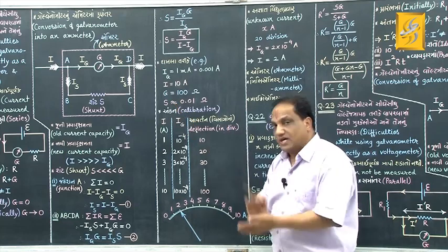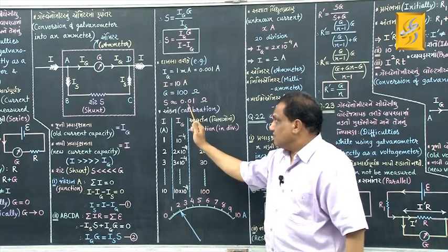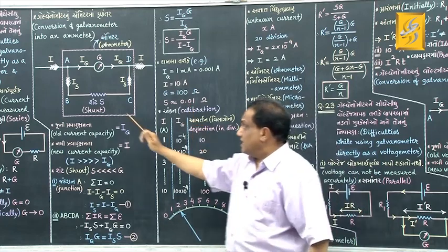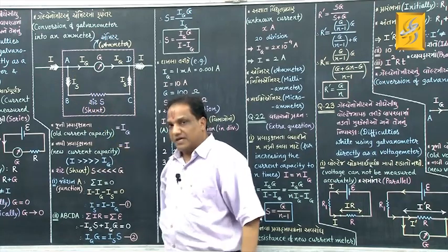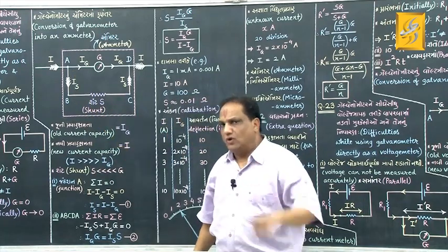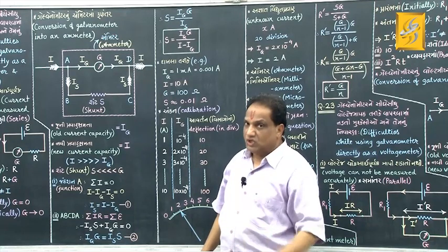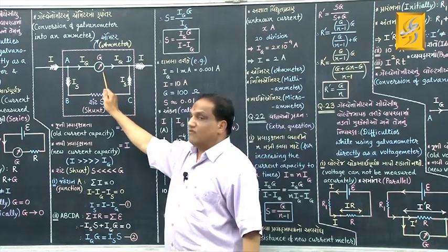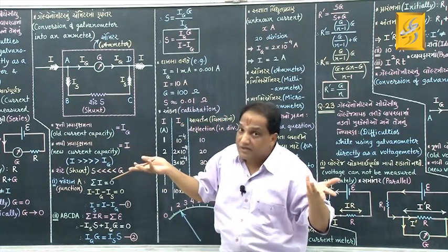Suppose you are finding this shunt, means it will give you ammeter? No. This much value of resistance you must connect in parallel with given galvanometer. Correct? Suppose you have connected, means it will give you ammeter? No. Still the main job is left out. What is that main job? To calibrate the scale of galvanometer in terms of ampere, because you require ammeter, correct?